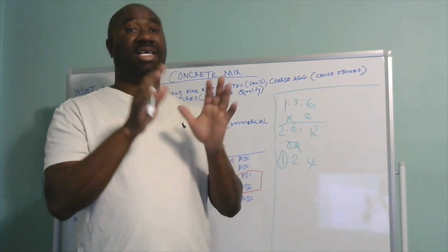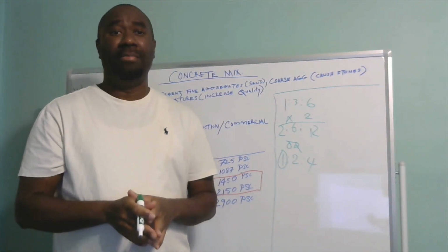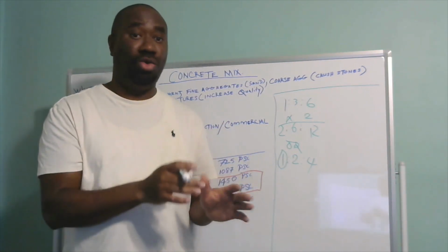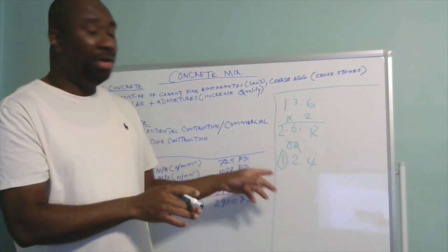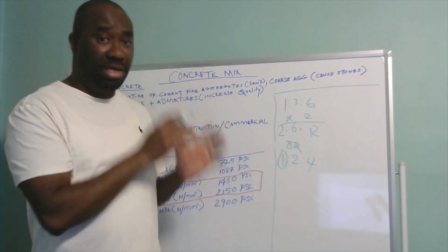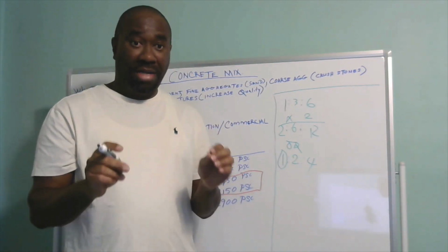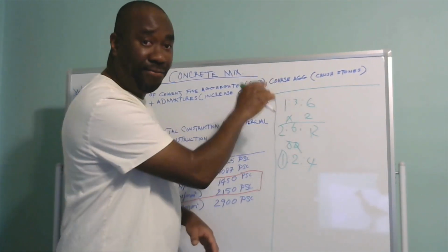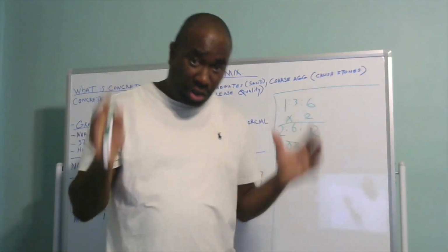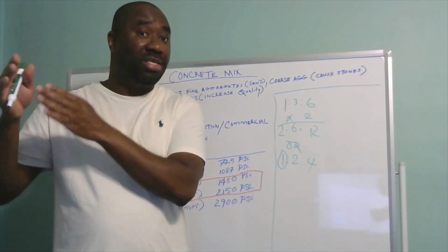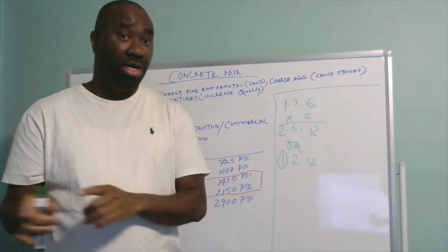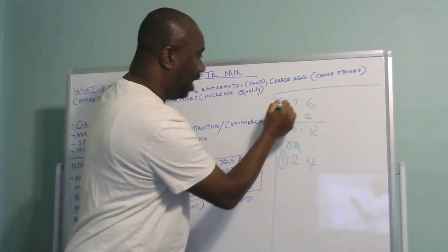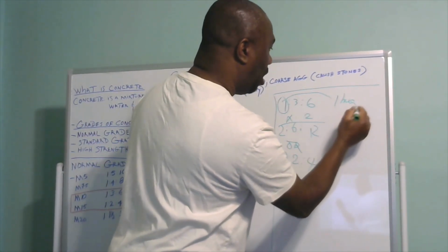I know that material is expensive and you want to cut back on your cement, but I'm saying to you that is a bad practice. It's better you try to shave a bit or two of your coarse or your fine aggregate, but do not cut back on your cement, because your cement really is a binder. The cement really is a glue that binds the coarse aggregate and the fine aggregate together to come up with a structural concrete that can withstand the loads along with the reinforcing rebars. So always remember that if you're using 1:2:4 or 1:3:6, this one here is not 1 bag of cement.